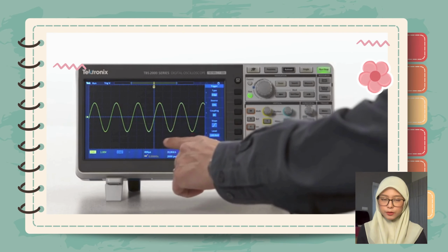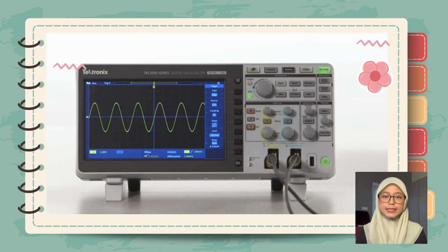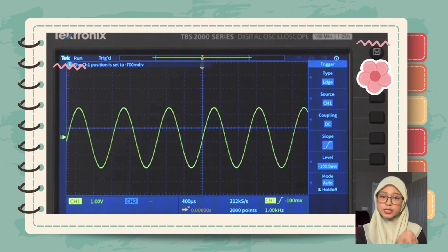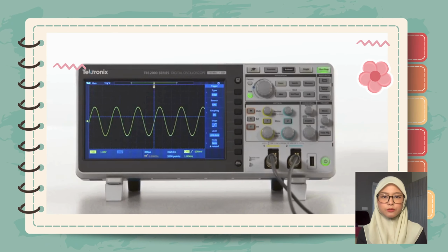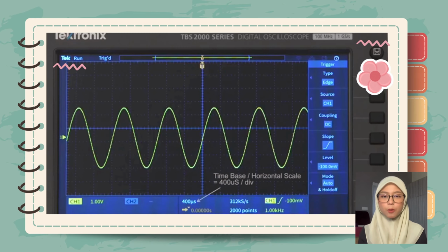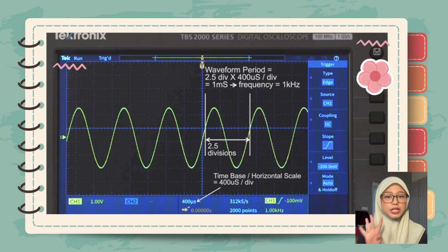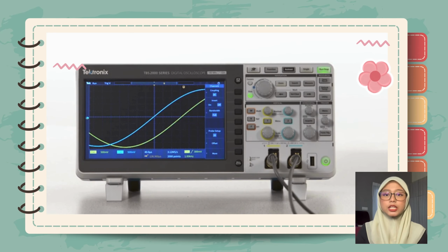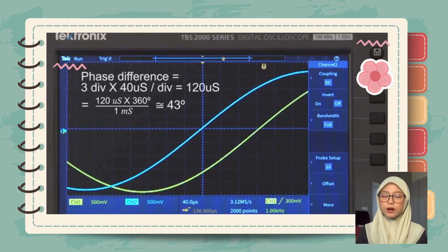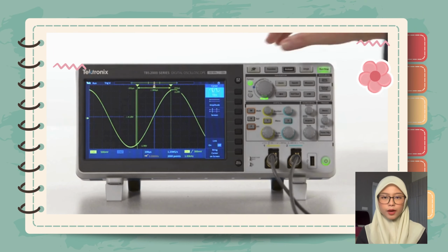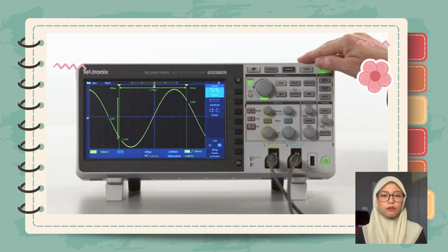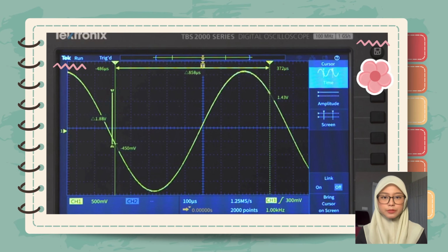High-resolution applications: since the rectangular window doesn't taper the signal, it provides the highest frequency resolution. This is valuable when observing signals with closely spaced spectral components. Lastly, transient signal analysis. The rectangular window is suitable for analyzing short bursts or transients of signal, where maintaining the full amplitude of the signal within the observation period is critical.